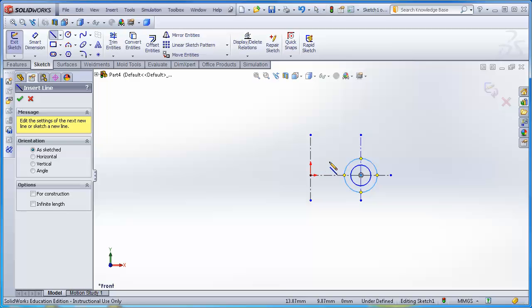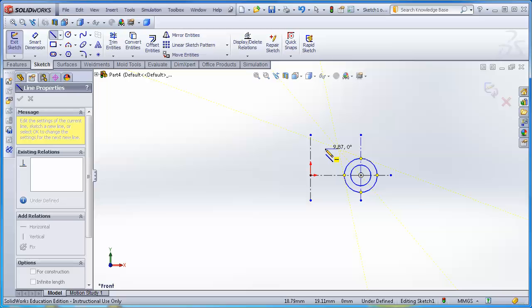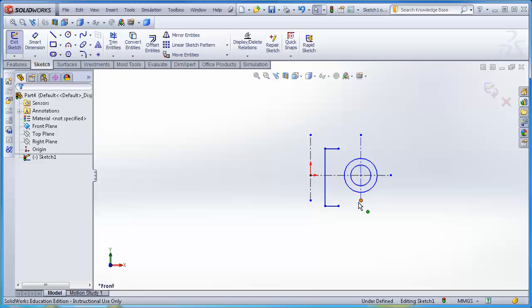I'm going to create a line that goes horizontal, down. I'm not going to snap to anything in particular, and back over, stopping underneath this point. Those would be my three lines. A key dimension in this part is that the distance from this line back to the origin, which contains the axis of revolution, is given as a diameter of 30.